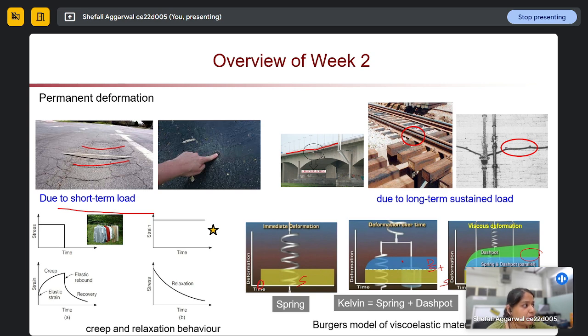And the second example is in wood. You might have seen the sleepers of any railway track. Nowadays these sleepers are mostly made of concrete. If we have wooden sleepers, normally they will be straight. Due to the continuous loading of our rails, there will be a permanent deformation here over time. So that is called creep in wood.